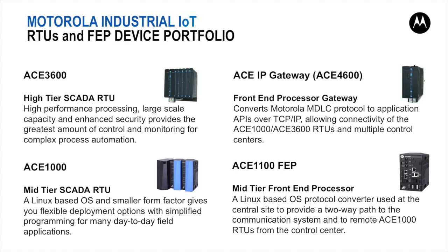This FEP supports a standard IoT protocol to communicate with the IoT manager and interface with the RTUs via MDLC. It also provides the ability to mirror all the information from the remote ACE1000 RTUs to the IoT central control center, so no direct interrogation from the control center to the remote site is required.